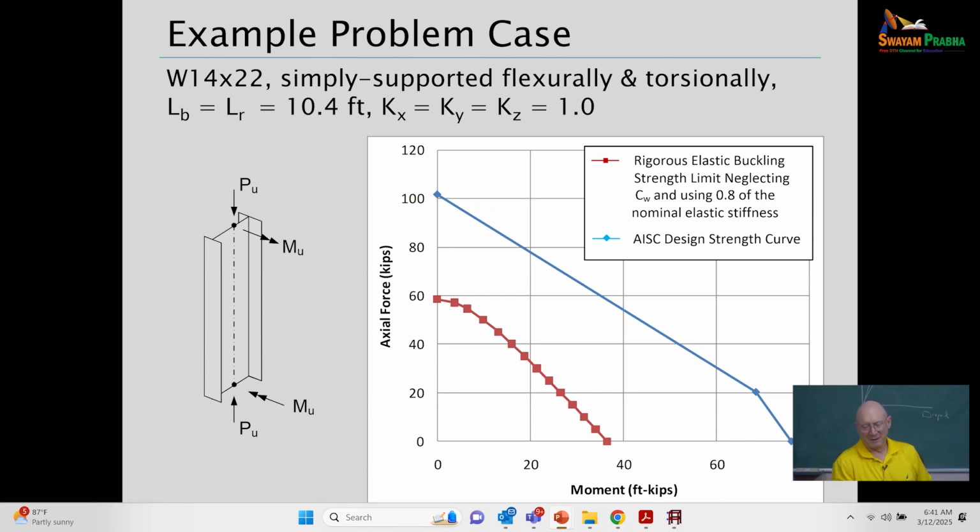And so that's basically a case where most of the software out there, very few of the software packages at present, will actually give you that 14th degree of freedom and give you a realistic representation of the torsional stiffness here.